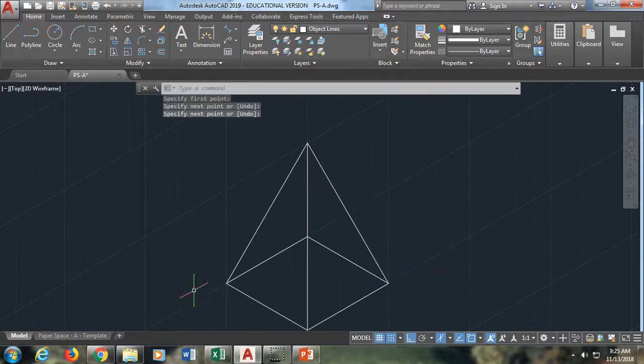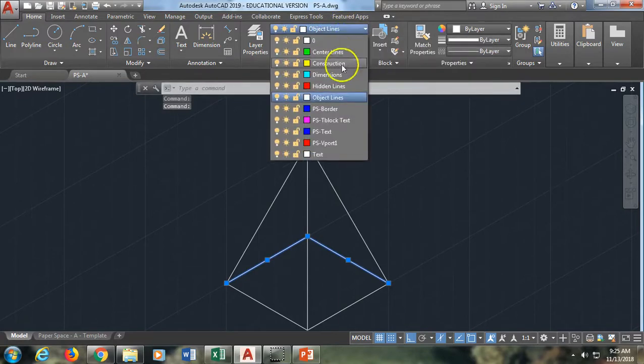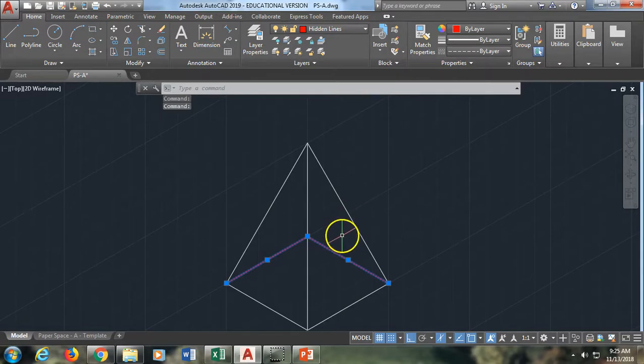Now in this drawing, there would be a hidden line for the back corner edge, but because the front edge goes directly in front of it, it dominates, and we don't have to draw that, but we do have to switch these over to being hidden lines, because you can't see them from the front of the object. So they become hidden lines, and we've drawn our pyramid.